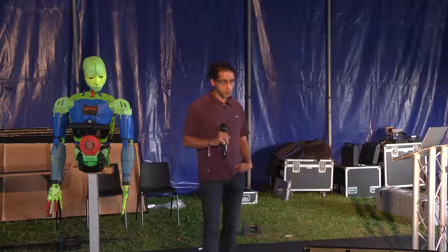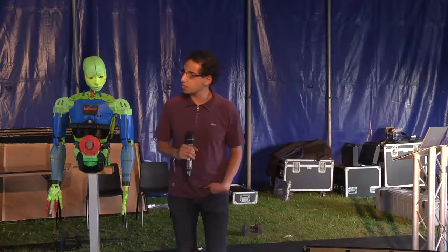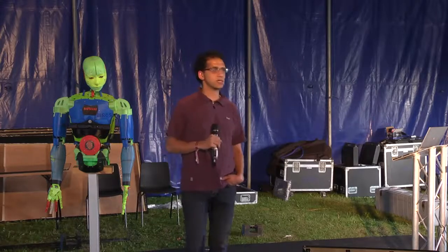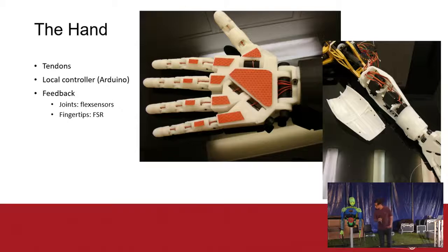Now in the forearm, in the original design, Gael used 5 servo motors to operate the hand. I did at some point, and right now the motors are not there, but at some point the motors were there. The problem with the original design is that you will have many cables that need to run up the arms and back to the controllers that normally sit on the back of the robot.